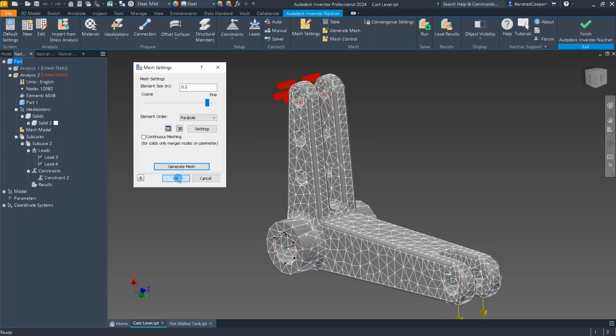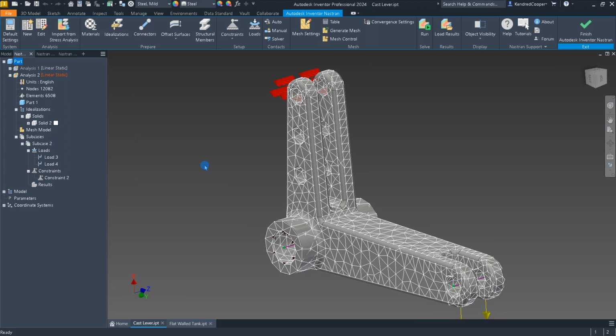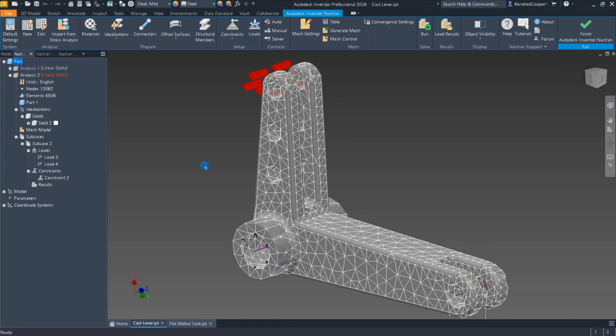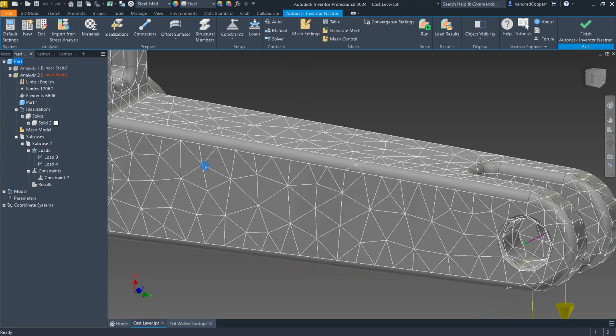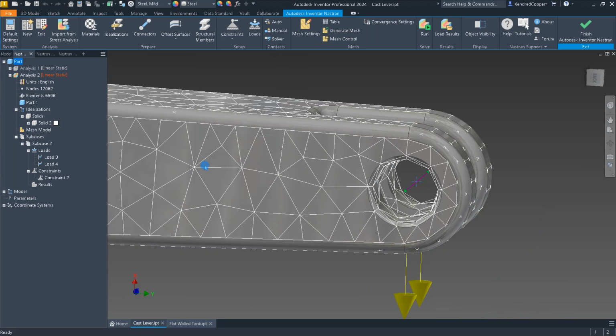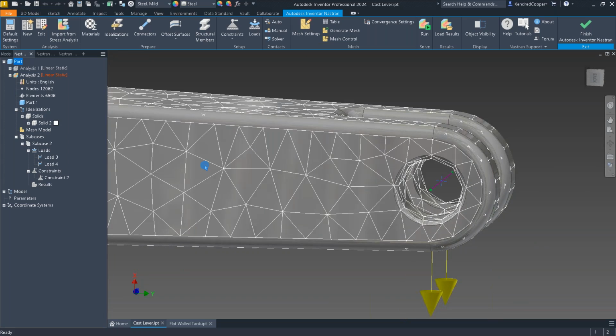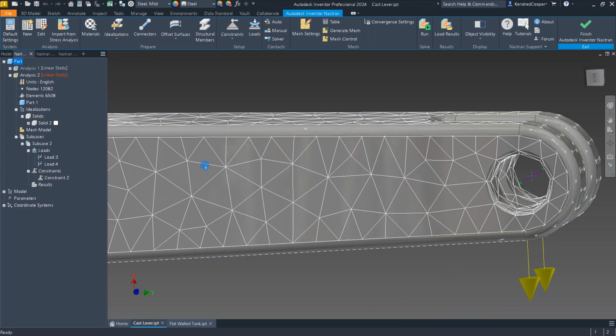And what you want to look for in a mesh is good, consistent pattern distribution and sizing. Now the sizing is going to fluctuate a little bit. When you go into smaller faces or round bore diameters, you'll see the mesh actually reduce in size. On a larger face, it'll get bigger in size.